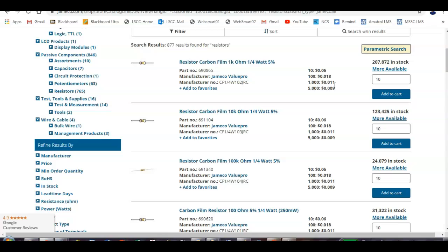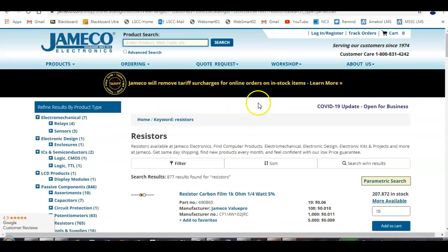I could use a rheostat. So here, it's going to cost me 6 cents, or it's going to cost me $5 for a rheostat. Well, you can't hardly get rheostats anymore because potentiometers can serve as a rheostat. So I pay $5 for a rheostat, or I pay 6 cents for a resistor, right? Well, it's actually not 6 cents because that's for 10. So that's 0.06 cents, or less than a penny a piece, these things cost, because they're mass produced. And if we went to eighth of a watt, we'll see that those guys are actually more.